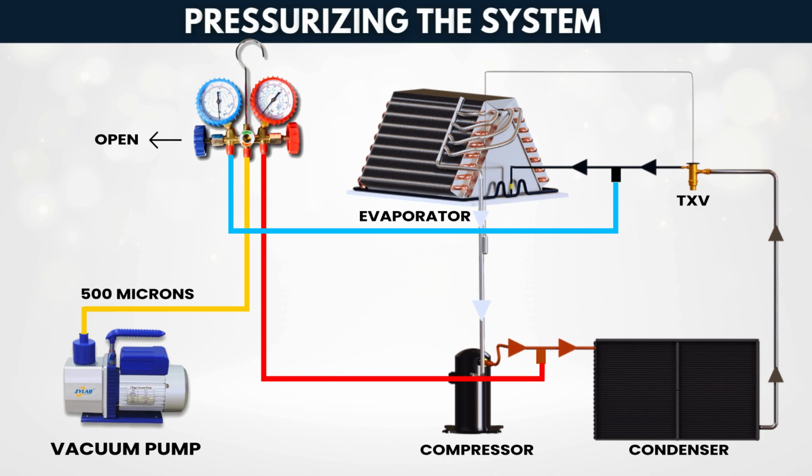So that's the full professional method for leak detection using nitrogen gas. Recover your refrigerant safely, choose the right test pressure, pressurize slowly, check with soap and detectors, purge during brazing, and always vacuum the system properly afterward. If you follow these steps carefully, you'll get accurate results, prevent damage, and ensure a long-lasting, efficient AC system.